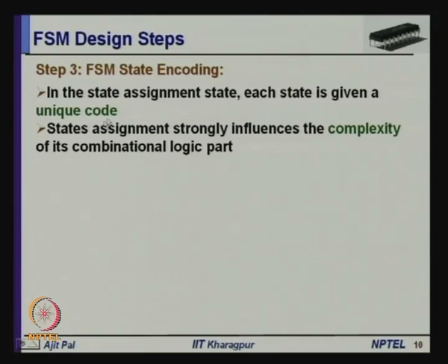And why state assignment or state encoding? Sometimes it is called state encoding, sometimes state assignment, both are the same thing. State assignment strongly influences the complexity of the combinational logic part. Depending on what state assignment you do, it influences the hardware realization of the finite state machine, that means the area required by the combinational part, or the delay of that circuit, and later on we shall see it will even influence the power dissipation.